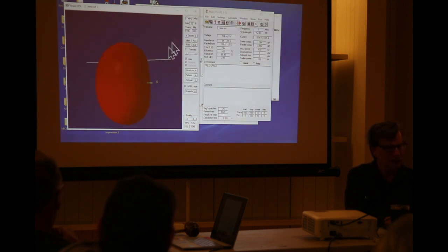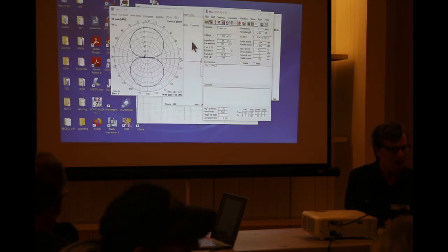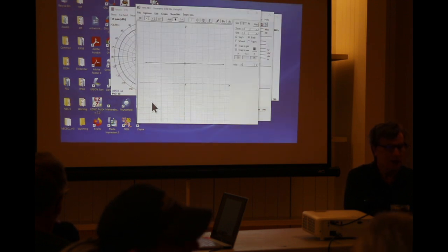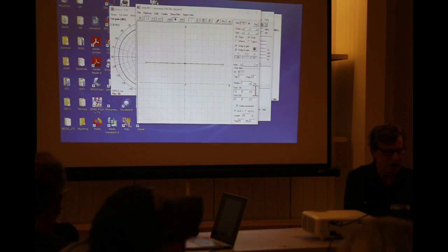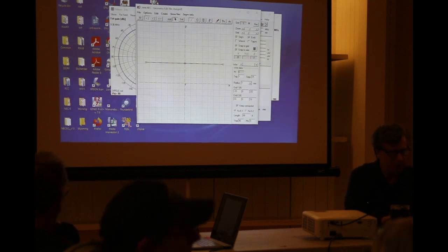Now, the reason this thing's poking through the middle here is we did not put this at ground level. When we start working with grounds, this will make more sense. So let's show what just having a ground does to a dipole. Let's close this out, and we'll change the height of this a little bit. Let's see, what is our height? Our height is our Z's over here, so we're only at 16 feet. So let's make this a quarter wave high. We'll put that at 33 feet as well, both ends.